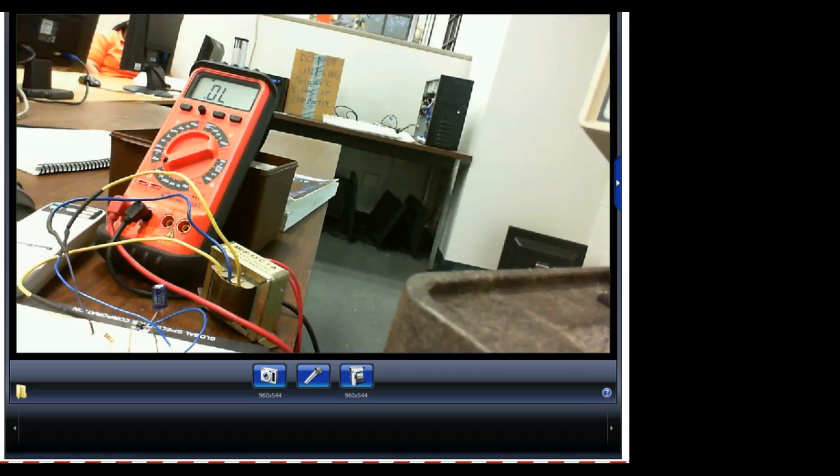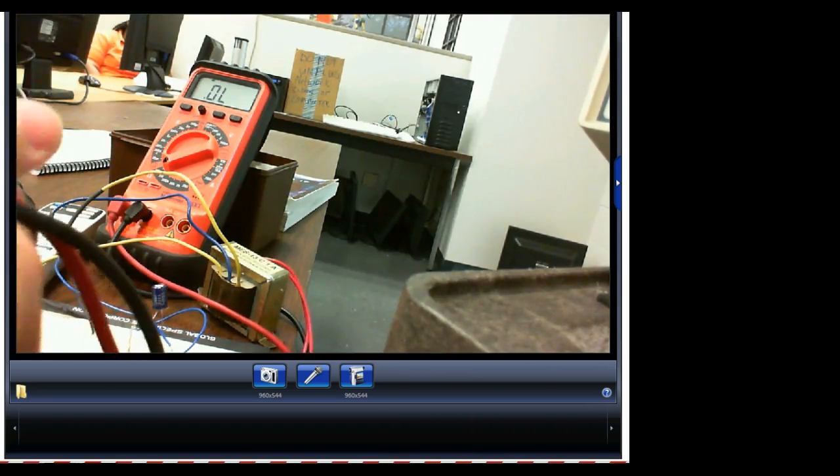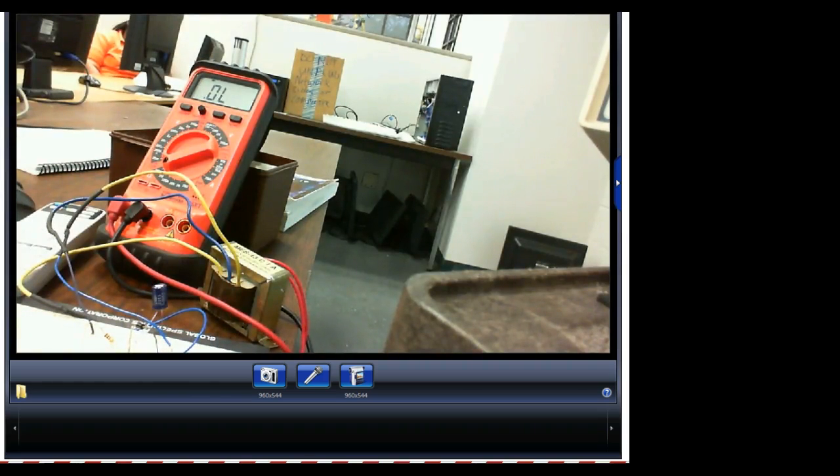About 0.7, it's going to be around there, for silicon diodes. Rectifier diodes are the ones we got in one of the labs, this is the one we should have done first. We'll do this once we finish, if we can get to the lab. We're not going to do lab unless y'all can understand what you're doing in there, right? You understand? So we measure this, it's measuring 1.195 volts.